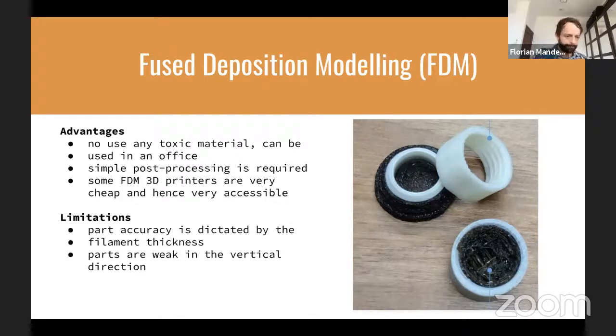Of course, you have some accuracy issues. When you make any moving parts, an axis or bearings or something, you always have a few tenths of a millimeter that you have to adjust. So never something super strong. And also these things tend to break much easier because they're layered together. That means they're not so strong in all directions.